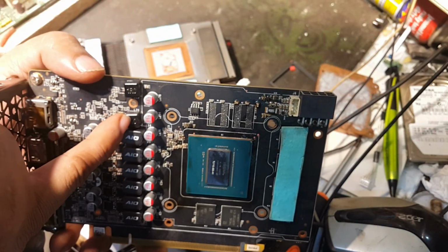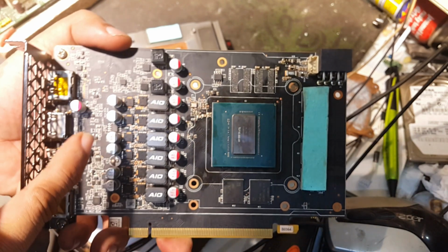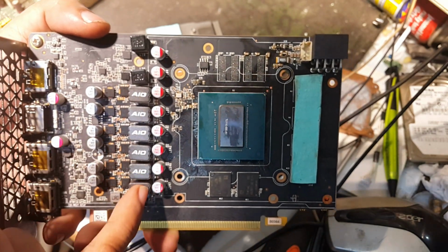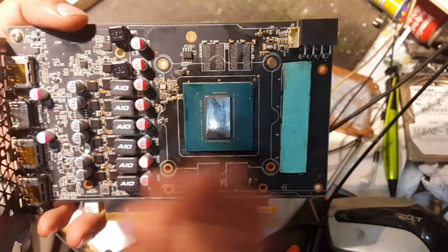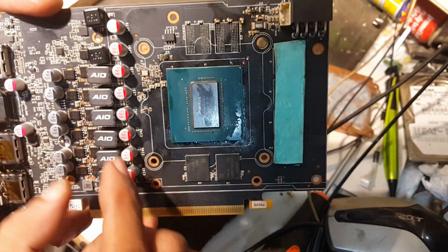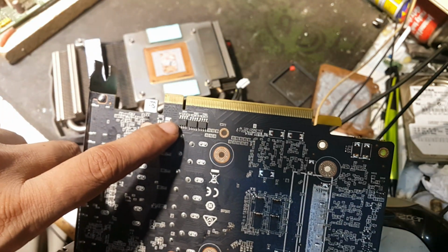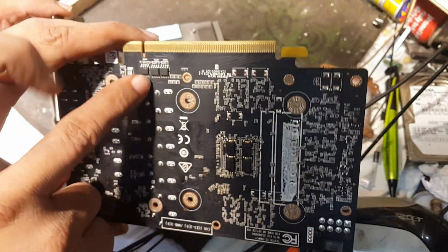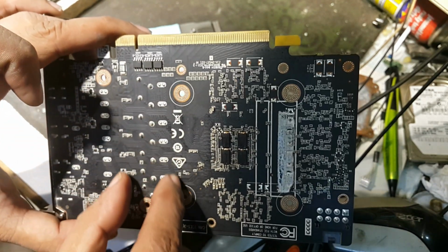This power supply was working, but this power supply was not working, and even these all power supplies were not working. So it could be a feedback issue, feedback from the GPU to the power supply buck controller. Buck controller chips are here. These three chips are controlling these FETs. So here could be a feedback from this processor that can cause these power supplies to stop. Okay, let's check it.